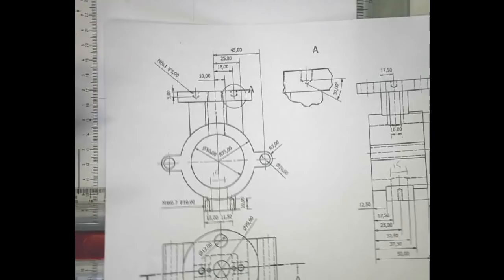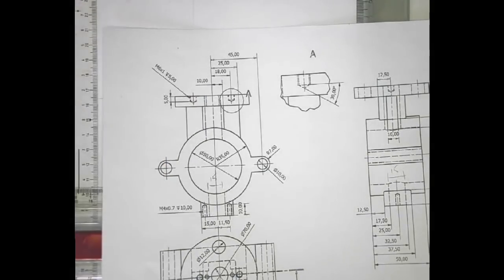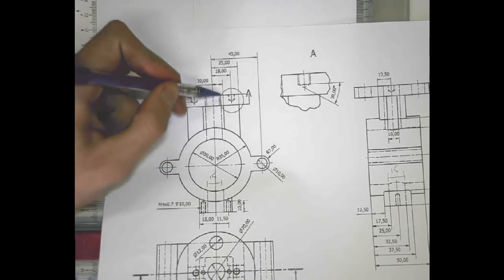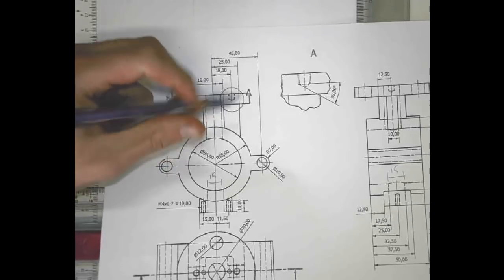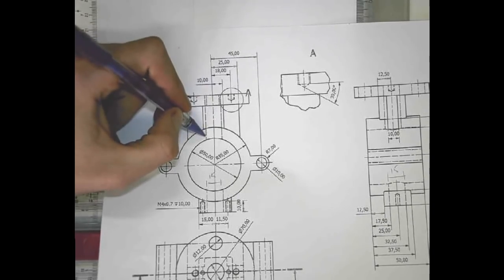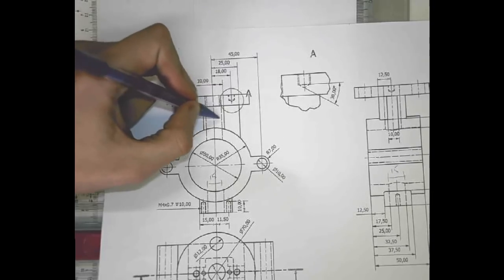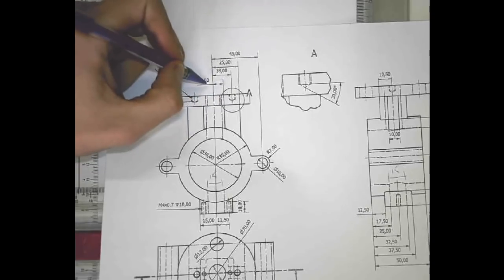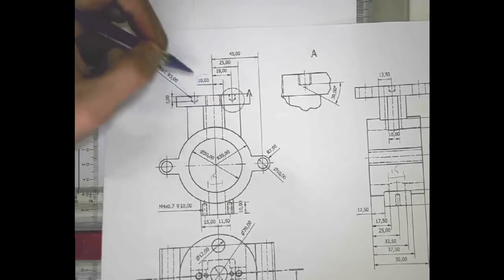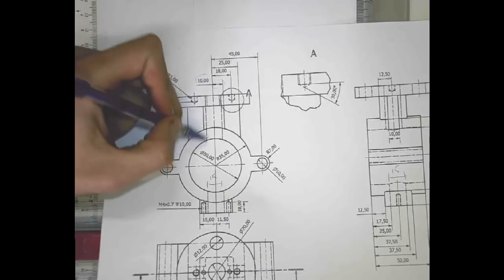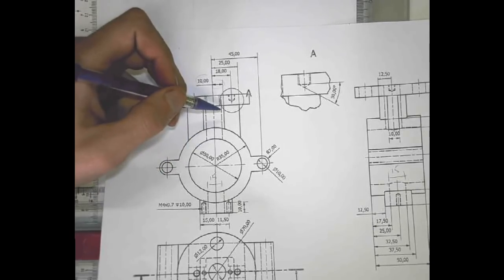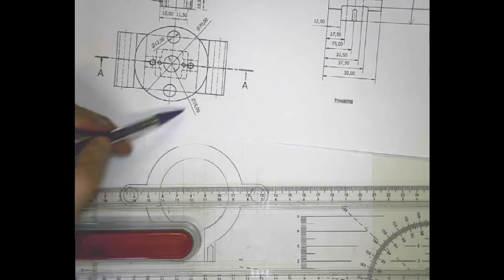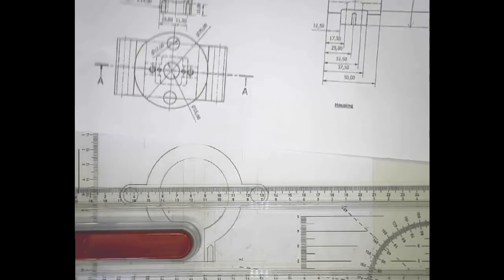And now we'll look at completing this section of the drawing. Because it's sectioned, these hidden detail lines will be visible edges, and we know that the width of this outer section here is 20 millimeters total, because it's 10 millimeters from the center line, and the width of this inside dimension is 15 millimeters as shown over here on our top view.